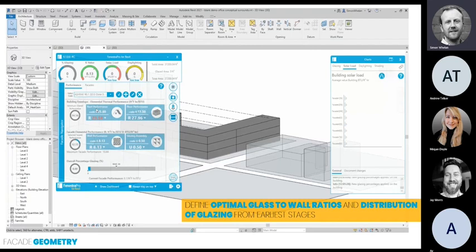So in other words, if the location of this project is set in Revit as Boston, let's just say, Fenestra Pro will look it up and say, well, Massachusetts has adopted, and I don't know if I'm right or not, but just for example, ASHRAE 90.1 2013, right? Boston is in zone 3, so it will offer you up the prescriptive performances, the window to wall ratios, and any other information around that particular code that might be relevant.